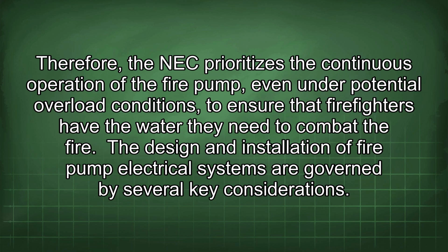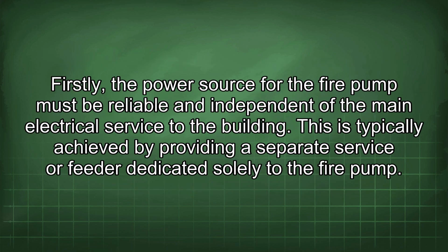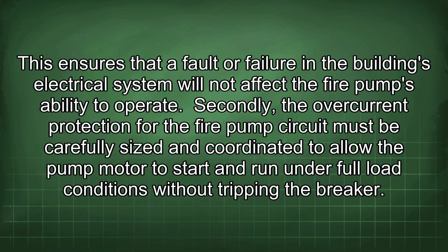The design and installation of fire pump electrical systems are governed by several key considerations. Firstly, the power source for the fire pump must be reliable and independent of the main electrical service to the building. This is typically achieved by providing a separate service or feeder dedicated solely to the fire pump. This ensures that a fault or failure in the building's electrical system will not affect the fire pump's ability to operate. Secondly, the overcurrent protection for the fire pump circuit must be carefully sized and coordinated to allow the pump